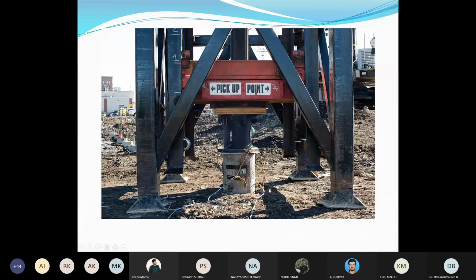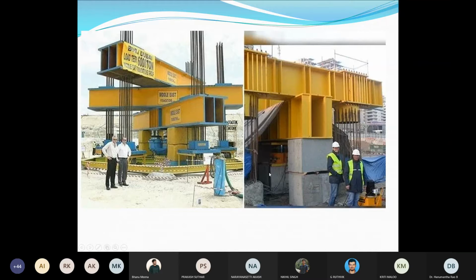So this is another close diagram of the pile foundation. Here you can see at the top a static load is mounted. In the middle is the pile and there is a hydraulic jack. I will show all the schematic diagrams of the pile load test. So this is a jack and this is some static load. This is also called a Kentledge bridge. If you refer to any soil mechanics book or foundation engineering book, they will write this typical pile load test as a Kentledge bridge. Kentledge is a person who proposed or developed this kind of method of pile test.